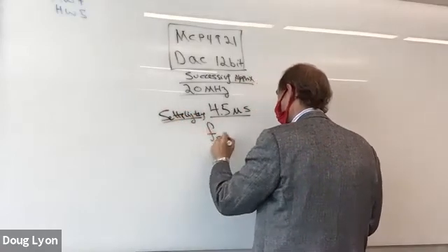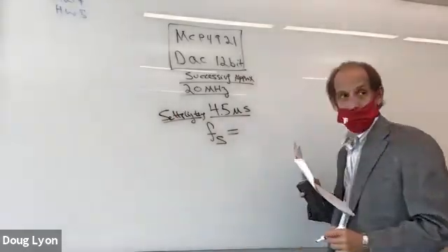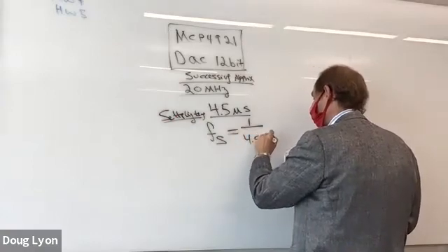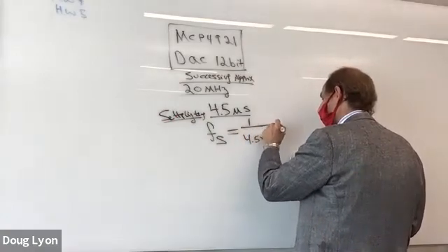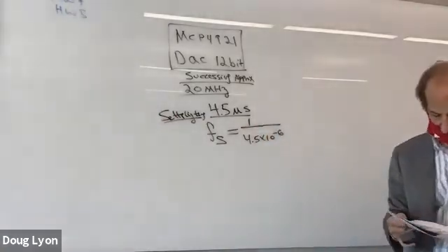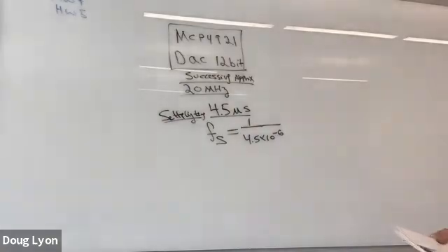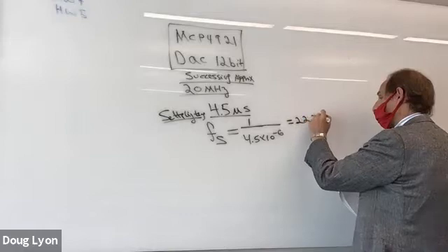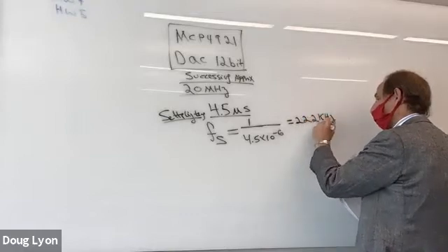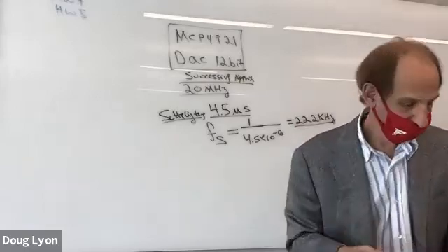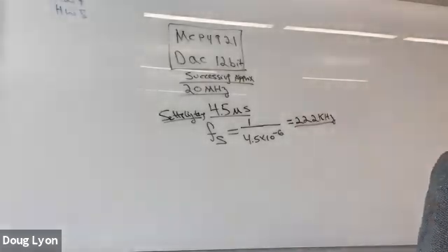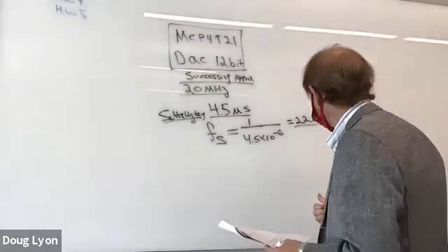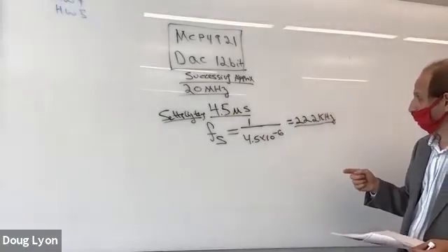what is the frequency of sampling maximum? And the answer is 1 divided by 4.5 times 10⁻⁶. And that comes out to be a number that runs about 222 kilohertz. So that's an upper limit. So now we've got 2 upper limits on the device. The dynamic range, it's a 12-bit DAC. The settling time, 4.5 microseconds.